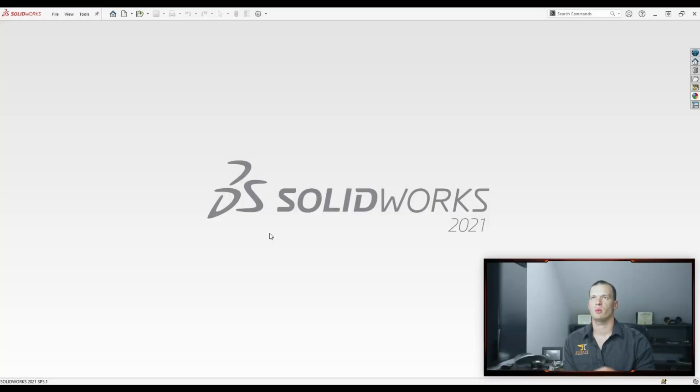So there's lots of different ways of doing top-down modeling. Basically, what you're trying to do is create a series of files that can pass information between each other and be very stable when it comes to solving and passing that information. Skeleton sketch modeling is a top-down modeling technique within SolidWorks. I'm going to walk through my workflow when I'm doing this type of modeling, and then talk about each step and why we do it along the way.